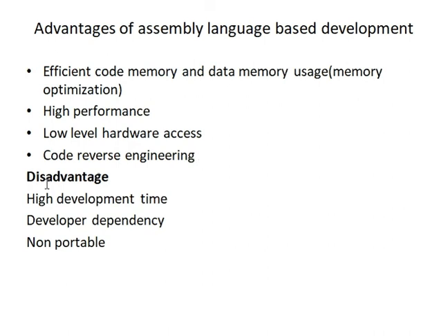Okay. And one of the disadvantages of developing firmware using assembly code happens to be high development time. Definitely it requires a lot of time. The reason is that you should understand the architecture of the controller first for developing in this language, and also writing assembly code is not that easy. Since you should be familiar with the instruction set for it to be optimized, it requires more time to develop this product into the market if you are using firmware developed using assembly code.